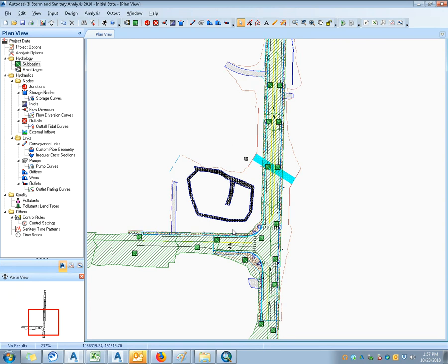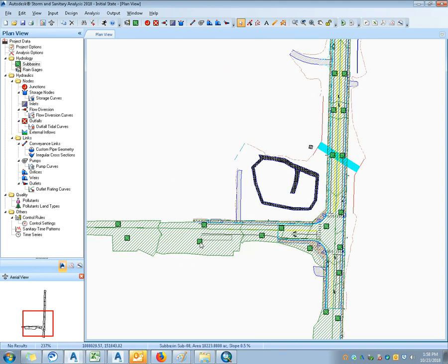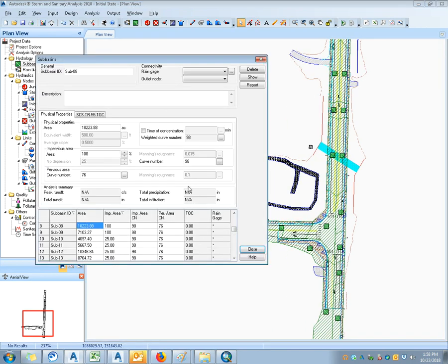Yeah. If you have a catchment file in CAD, maybe to Jeff's point, you could use the method where you bring in just the point data for the connectivity and then background it with just a line work file for the catchment. That might be a way to go. Totally. But I think for me, the visual of it is really helpful.